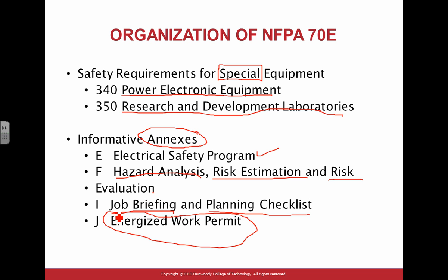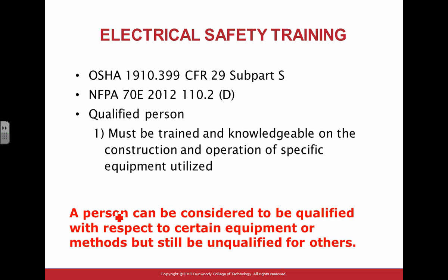Really, every time I want to go measure the voltage here, 50 volt or 70 volt or 120 volt, I'm not going to write a whole big two-page energized work permit and have five or six managers sign it, plus the electrician and the technician. So day-to-day testing things are excluded. Now you go open a switchgear and start putzing around with it and adding another circuit to it, that needs an energized work permit. So these are the things that we're going to be doing.